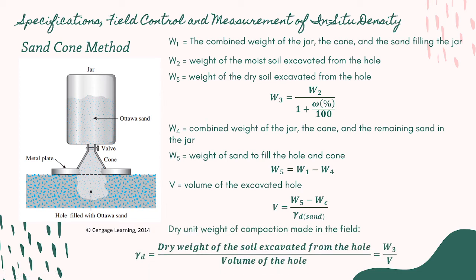And then now that we already know the dry weight of the soil, the weight of the dry soil excavated from the hole, and then similarly the volume of the excavated hole, we can now determine the dry unit weight.